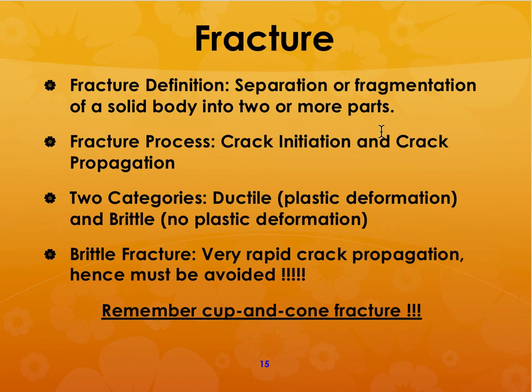You can either deform it in a plastic or a ductile manner, or it just fails like that with no strain at all, no plastic deformation at all. And in this case, brittle fracture means it propagates the crack extremely fast, almost at the speed of sound. And in that case, especially if you are designing a component, you should avoid that at all costs.